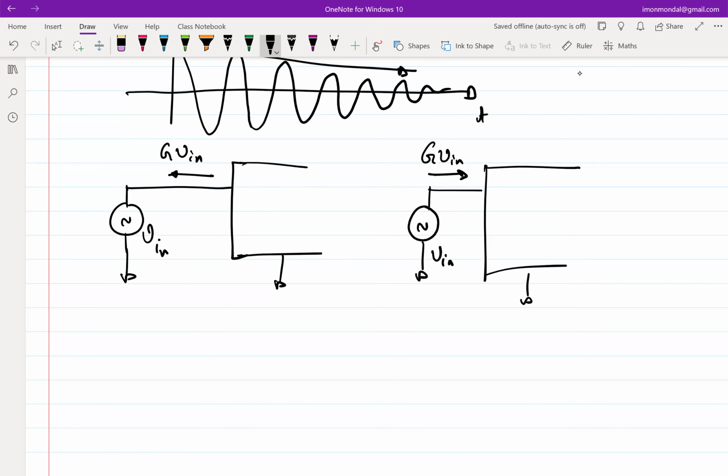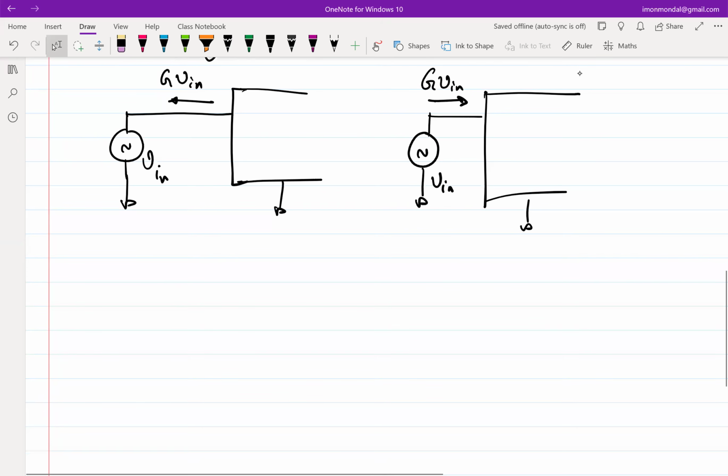Yeah, so diode connected. So why does diode connected solve the problem? Why does a diode connected transistor help? In the sense, what I'm asking is, when you say diode connected, you are essentially saying that I have a voltage controlled current source, because a transistor is a voltage controlled current source. So I assume I have a voltage controlled current source ready. A transistor is a voltage controlled current source because if I apply V in, I'm going to get a current which is proportional to V in. Which direction? Going out or going in?